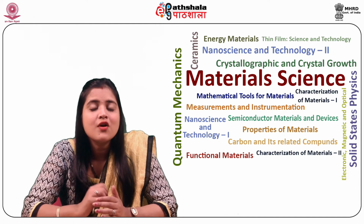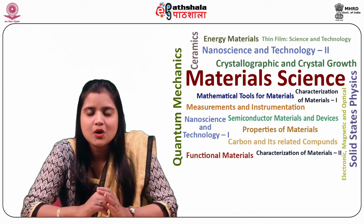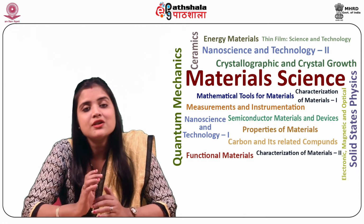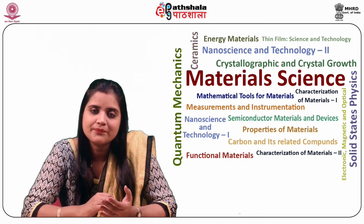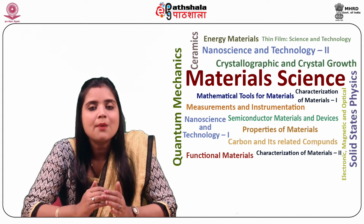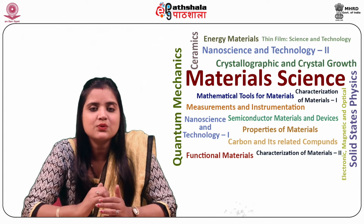Hence, the study of electrical and dielectric behavior of thin films helps to gain insight into the structural properties of films, which is important for practical applications. The characteristics of thin films and different aspects of the growth parameters and the growth mechanism can be understood well by the electrical characterization of the films. Several techniques are being exploited for these studies. In this module, we will study briefly some of them, such as Hall measurements, contact method for resistivity studies, current voltage, and capacitance voltage studies.